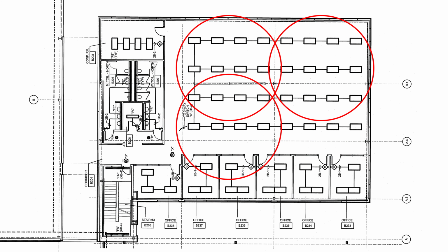The design begins with the placement of red circles representing the occupancy detection range of Amatis sensors. Once these circles have been placed and adequate coverage of the space is ensured, sensors are located at the center of each circle. To maintain an easy-to-read design, the circles are then removed before the design is completed.